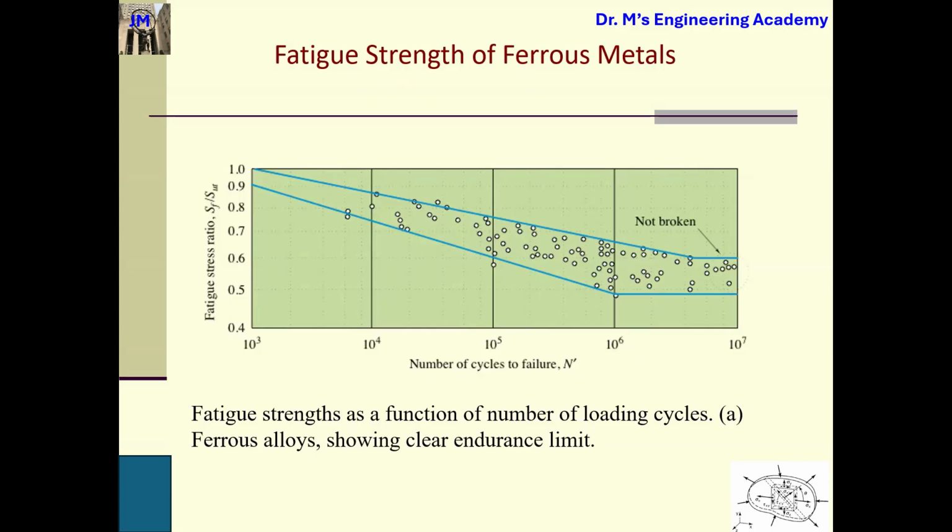The physical significance of the endurance limit, I want you guys to listen, is that if you apply a stress level that is lower than this endurance limit, then theoretically, no matter how many cycles you apply to this specimen, the specimen will not fail.